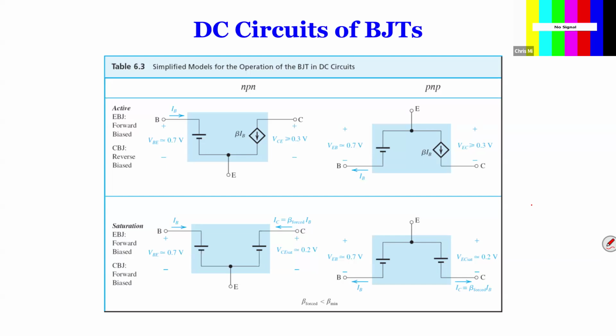I might be getting ahead of us at this point, but how is this second one affected in the saturation region? This is just an ideal version, when we have the saturation resistance model. Oh, you mean when you have the Early voltage, the Early resistance? It's going to be the same here. Yes, it's going to be a resistor in parallel.